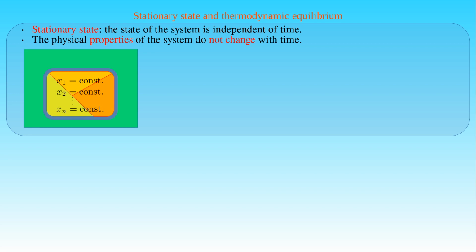The relationship between the state of a system and the transport processes between it and its surroundings is complex. Even if the transport of mass, energy, or momentum is prevented between the system and its environment, it does not follow that the system is necessarily in a stationary state. For example, any exothermic chemical reaction in an insulated thermodynamic system, releasing heat and changing the chemical composition within the system, modifies its state. Inversely, a thermodynamic system exchanging mass, energy, and momentum in the form of work with its environment can still be in a stationary state. That is, a mass or a heat flow between a steady-state system and its surroundings does not necessarily change its physical properties with time.